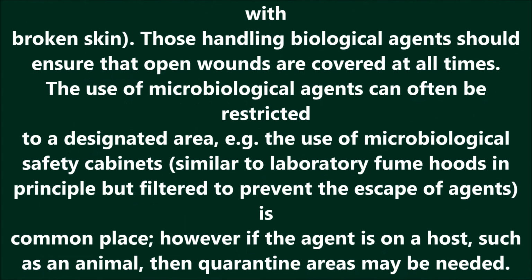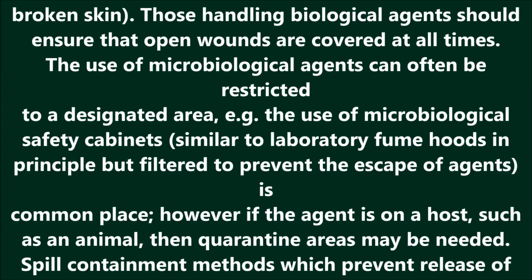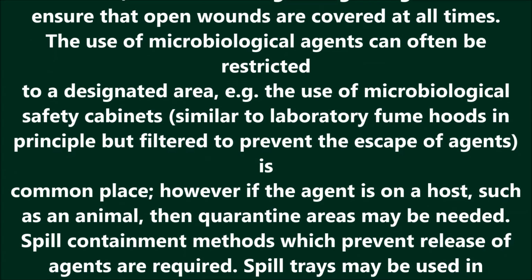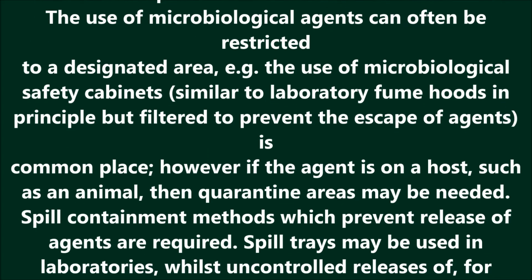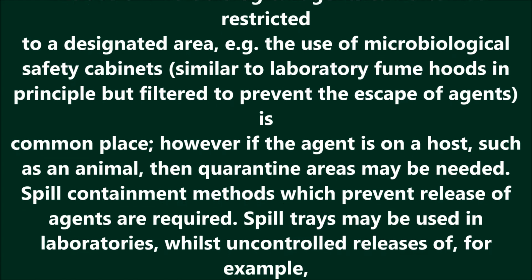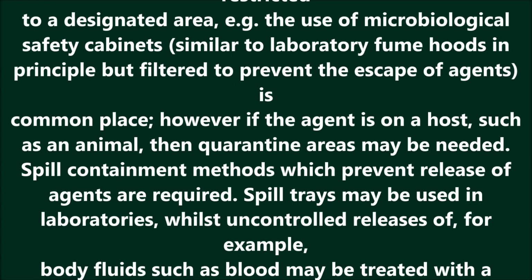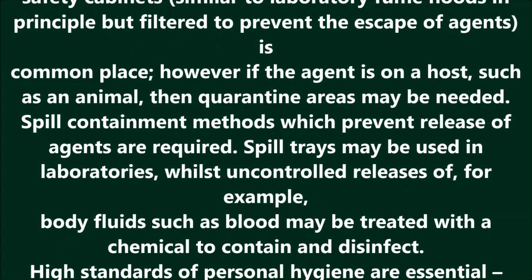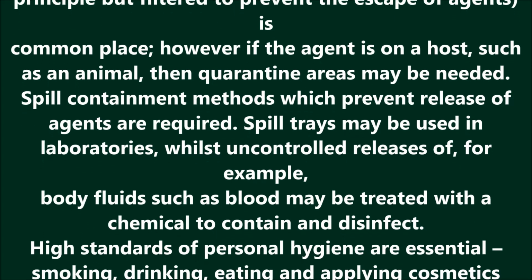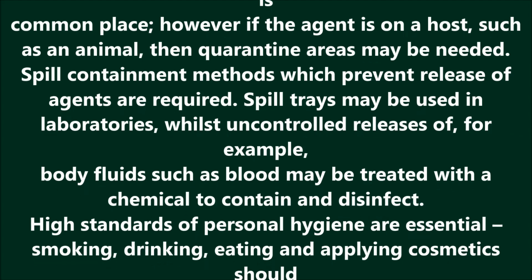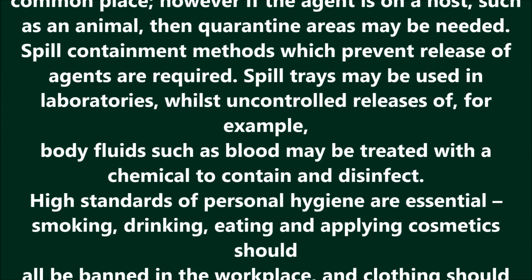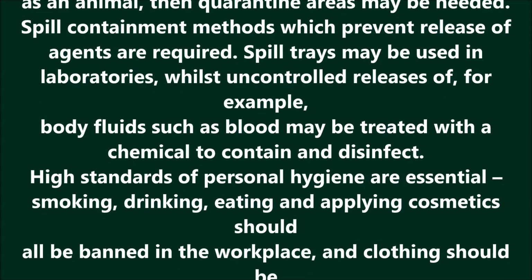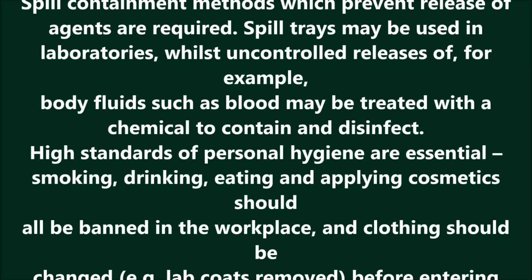The use of microbiological agents can often be restricted to a designated area, for example the use of microbiological safety cabinets, similar to laboratory fume hoods in principle but filtered to prevent the escape of agents, is commonplace. However, if the agent is on a host, such as an animal, then quarantine areas may be needed. Spill containment methods which prevent release of agents are required.